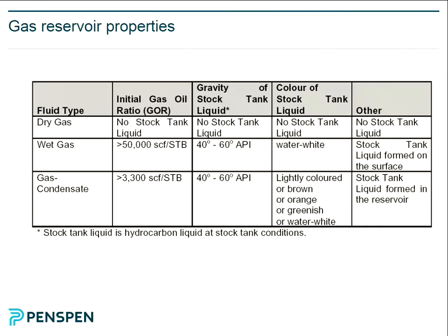So production separator and then the oil treatment separator. With the production separator, you're splitting the product into three different things. Gas coming out the top to the gas treatment, and then you've got oil to oil treatment, and then you've got water treatment. Now water, you've got no use of the water. It's possible you could re-inject it, but normally you dump it to the sea.